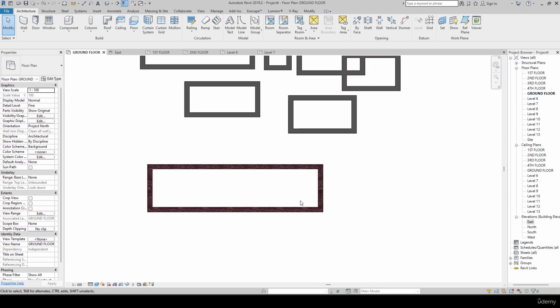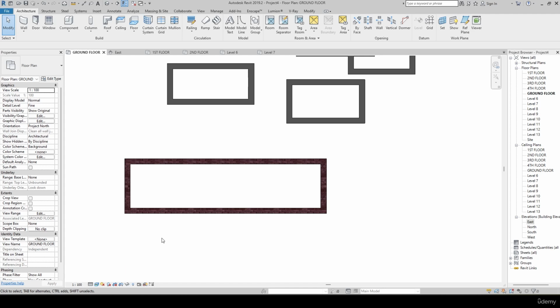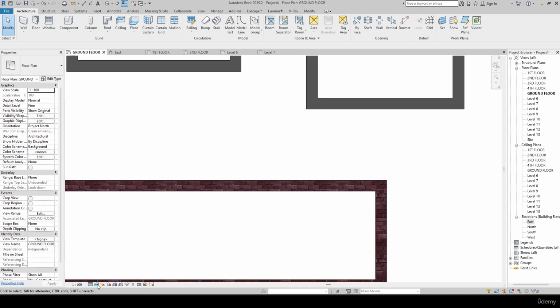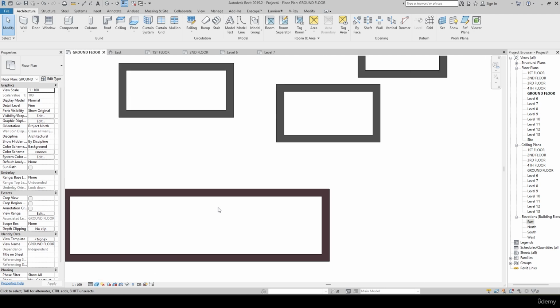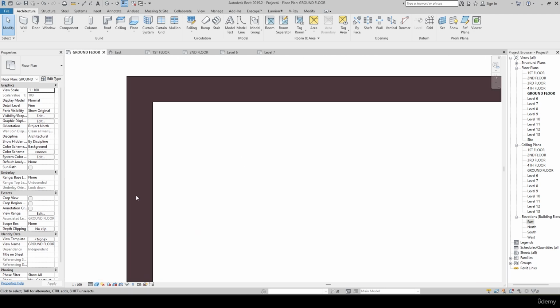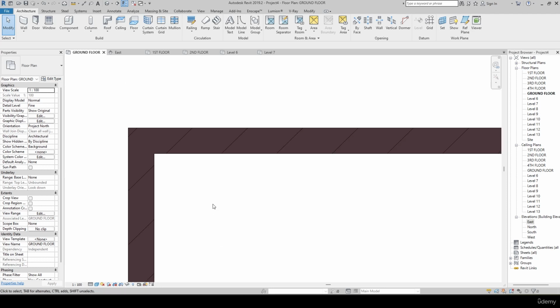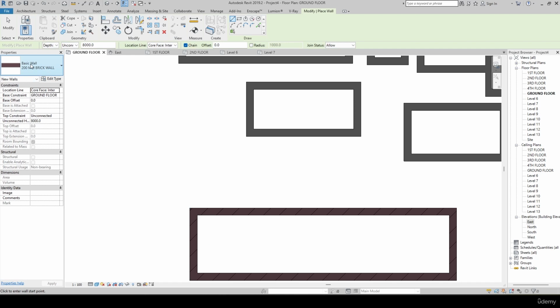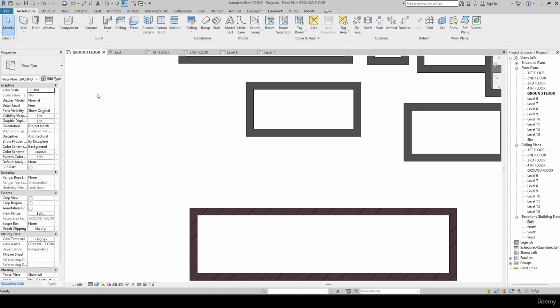Right? So then I'm having one more, let us say for example in this wall there is no plastering here. I will keep it as the consistency color. So in this wall I don't have any plastering. I want to add different layers to this particular wall. So in order to add, what I have to do, again I just need to go to the wall section, or maybe the wall WA. I have entered the command WA.